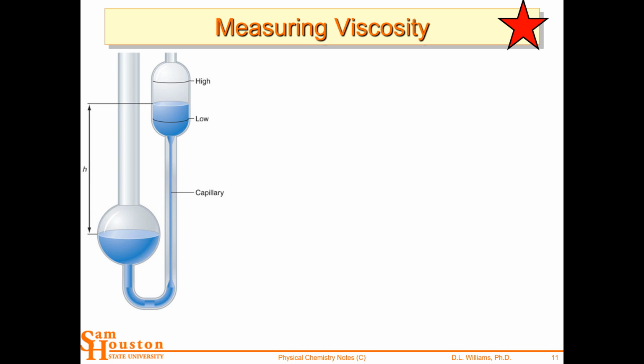Now, how do we measure viscosity? This is one way. We've talked about the falling ball viscometer. Modern instrumentation has this motorized version. This is really the best way, using these motorized versions. The reason that the motorized viscometry or rheology instruments are best is because it's frequency dependent, right? If I turn this slowly versus quickly, I get a curve in terms of the viscosity dependence upon frequency.